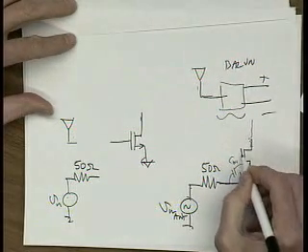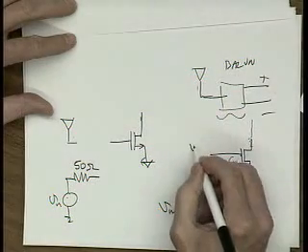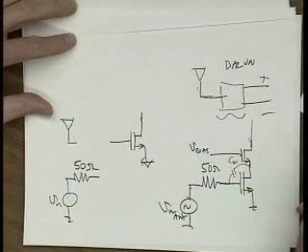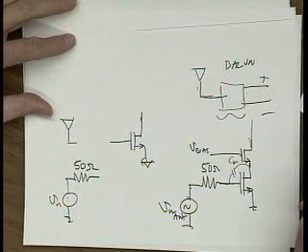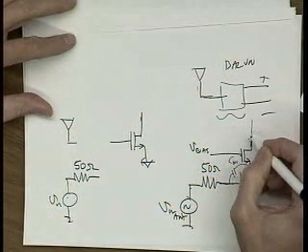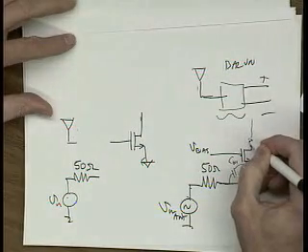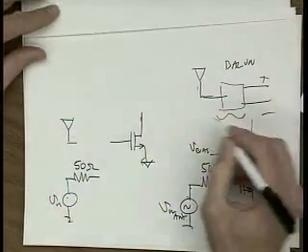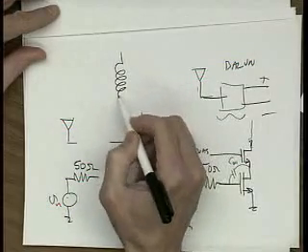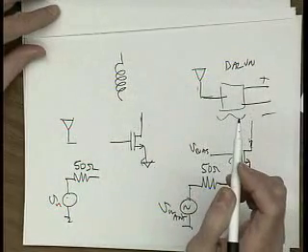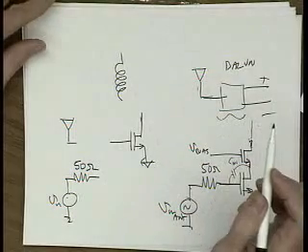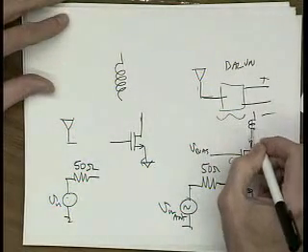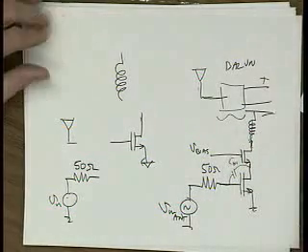So let's cascode it. Go out to some V bias. So that gets rid of this Miller multiplication effect. Okay, now let's do a load up here. So now what could we put? We could put a resistor here. But remember, I've got a new element now. I've got an inductor. And here's where inductors are just super. What you really want to use as a load is an inductor.